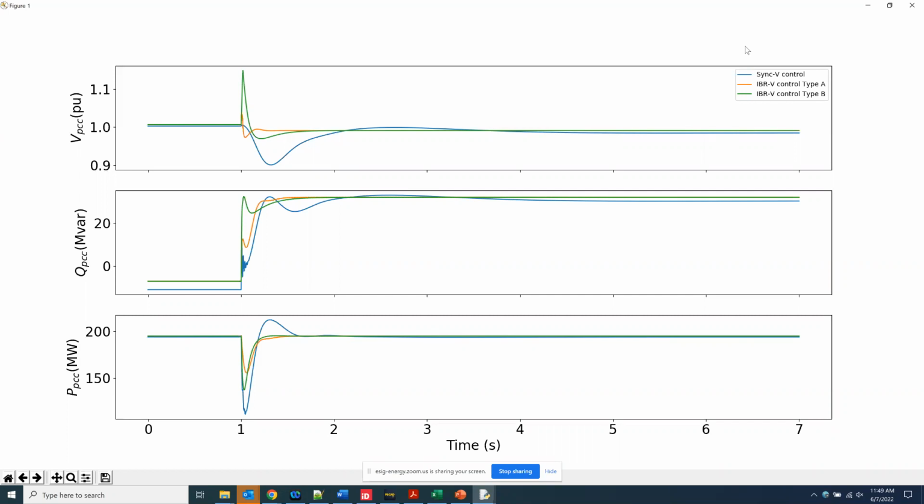So what made that synchronous machine a grid forming machine was not only the fact that it's inherently a voltage source behind impedance, but also that it had the excitation system. And probably later when we talk about power, it also has the inertia. Exactly. So if we recognize it from that perspective and translate that to an inverter, we can change this into a service-based requirement, where we want grid forming inverter-based resources to also have fast voltage control, fast frequency response, and so on at the inverter level, rather than saying that a grid forming inverter consists of control elements XYZ or doesn't consist of control elements ABC.